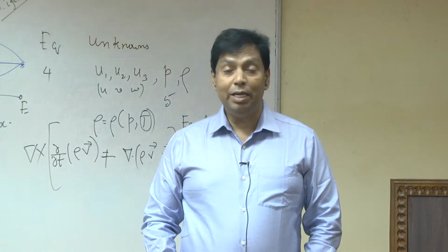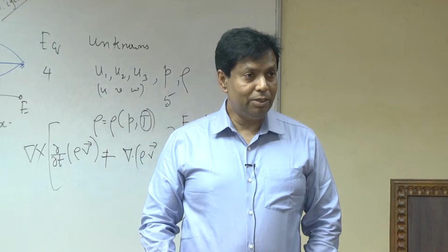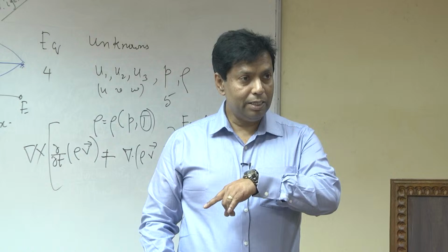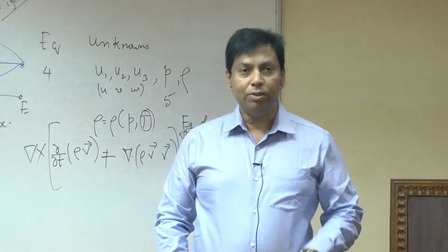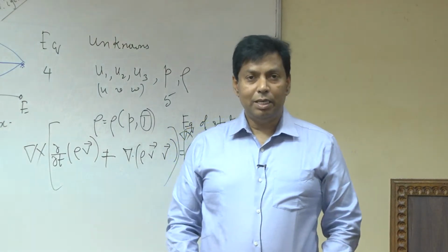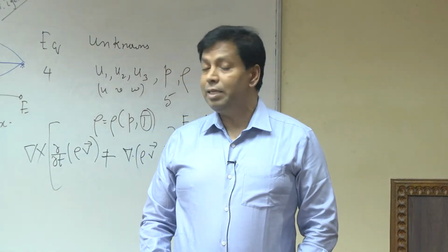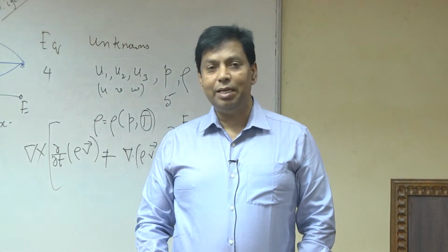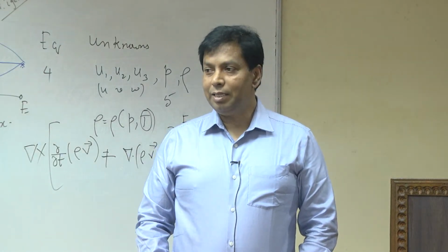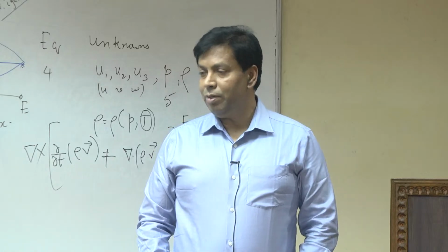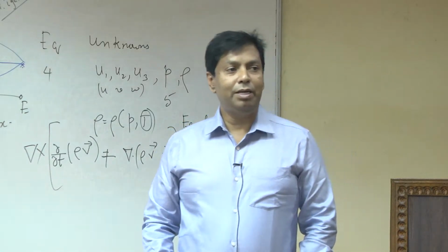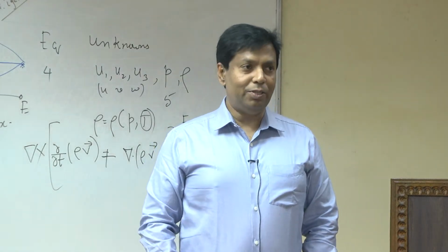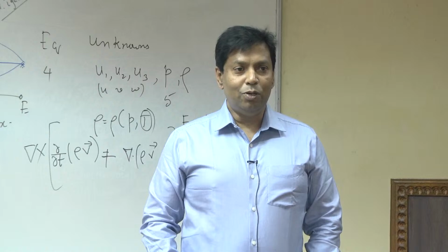I think we already have our geometry, right? Geometry and meshing, and he will show you, or you will create the geometry here. Good. Okay. So, he will start from the geometry and meshing, then the boundary conditions, and then the solution. But he will use a very coarse mesh so that we can get a very quick solution. Otherwise, it will take a long time for the solution, and then we won't have any time.